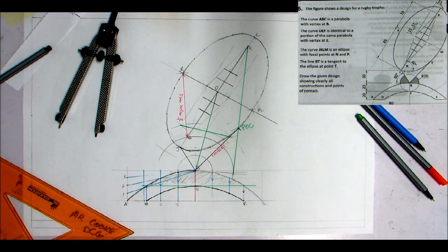So I copied all the points, any points above that, and I moved them all down by 20 millimeters. Very simple. Okay, so the end point here where the green line is, brought them down, they will give me D and F, that point, that point, that point, and that point, moved them down by 20 millimeters, and that gave me my curve. Okay, the ellipse should be fairly straightforward. Once we know the rule, half the major from the minor finds you what? Focal points.